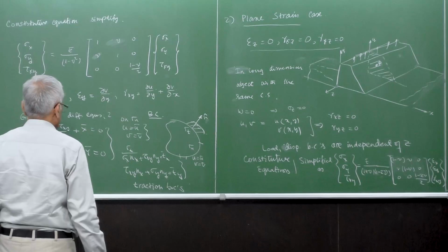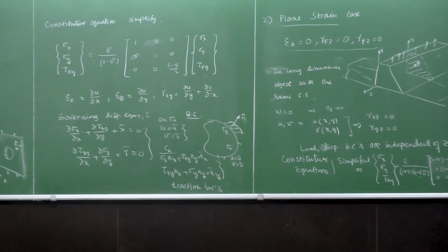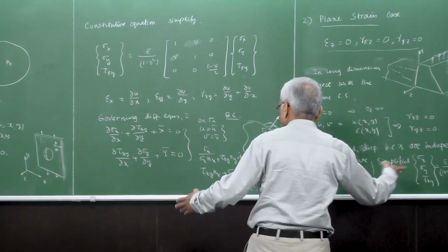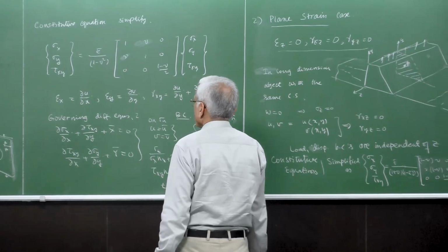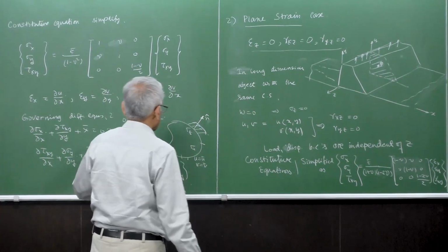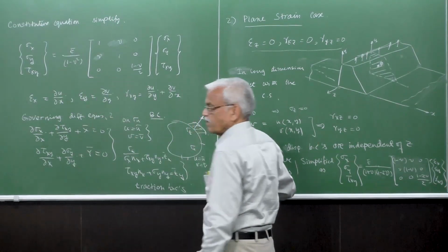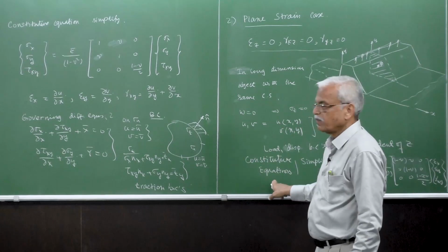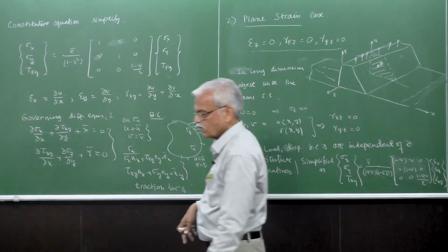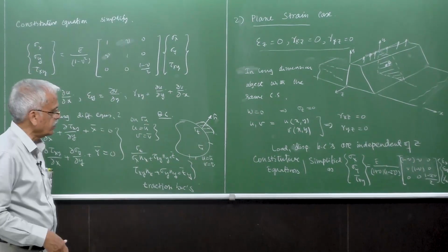Okay, so we have seen that the 2D problems can be put almost very similar to each other. The strain displacements will remain the same. Even though I did not write the equilibrium equations here, the equilibrium equations will be the same, except that the constitutive equations will be different. And if you want, we can even put it